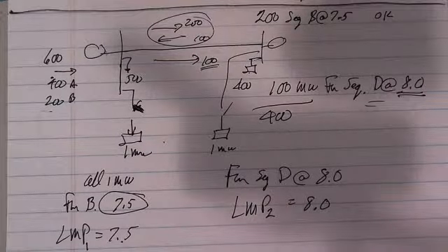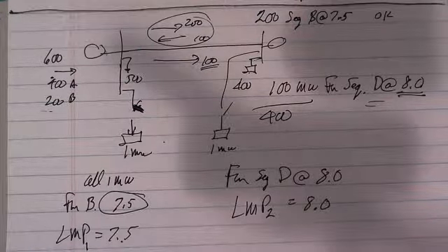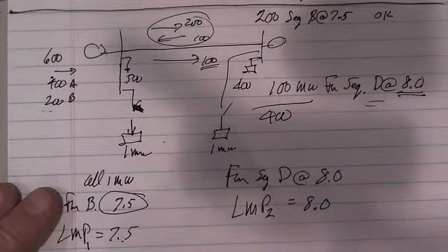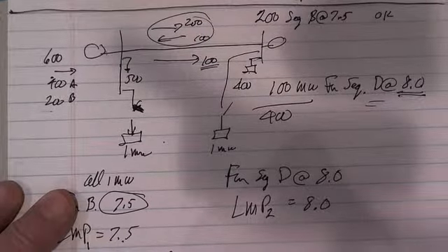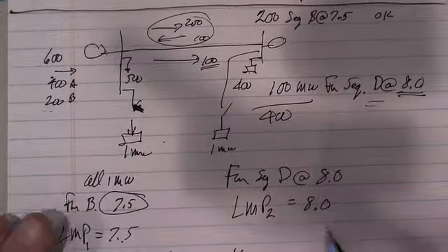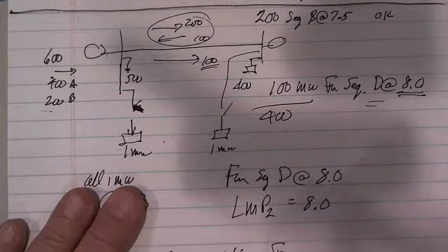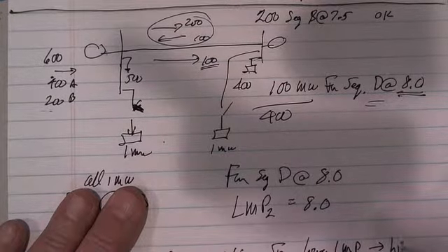So we now show that with transmission limits affecting us, the locational price is different. And the flow on a constrained line, and that's what we have there, that line is constrained, is always from the lower LMP to the higher.